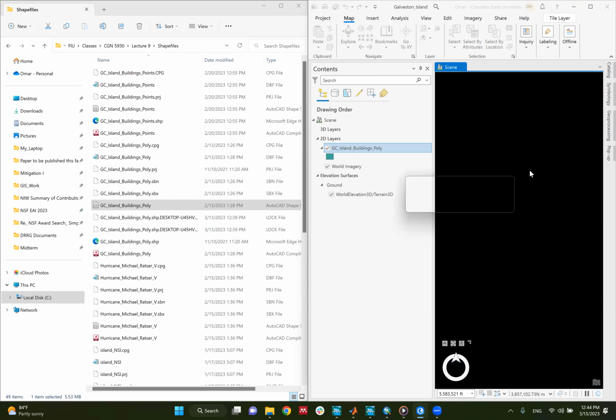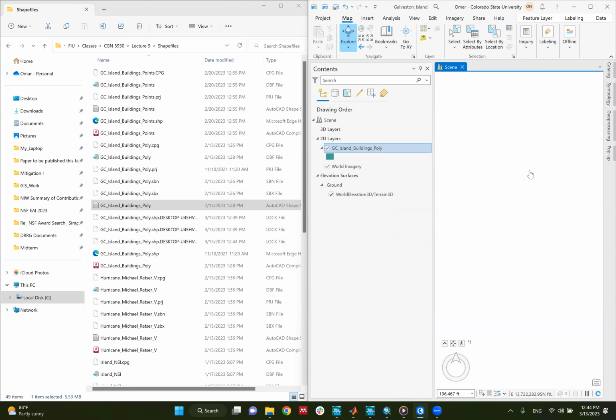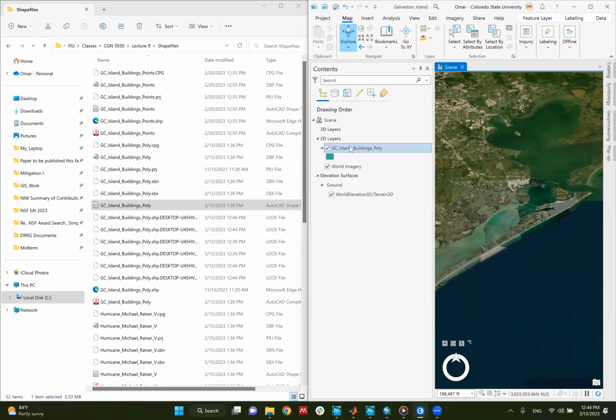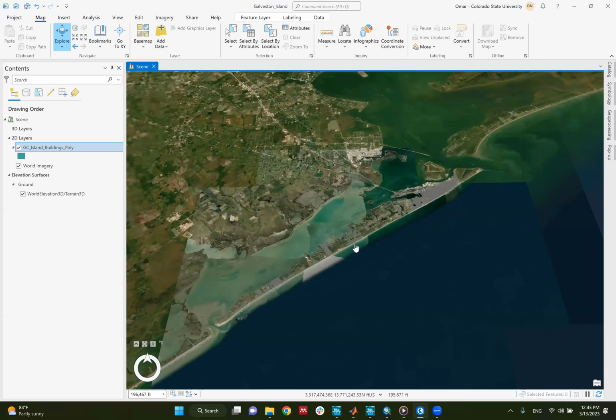It will be dropped. Any data, like sometimes when we deal with a community, you have a bunch of data about the buildings, about the networks, power, water, transportation. So you have your ArcGIS on the right, and on the left are the folders, and you keep dragging rather than open a folder, choose a folder. Yeah, so I drag the folder, it takes some time. It recognized that this is a 2D layer. This is a 2D layer. And the shapefile will be here.